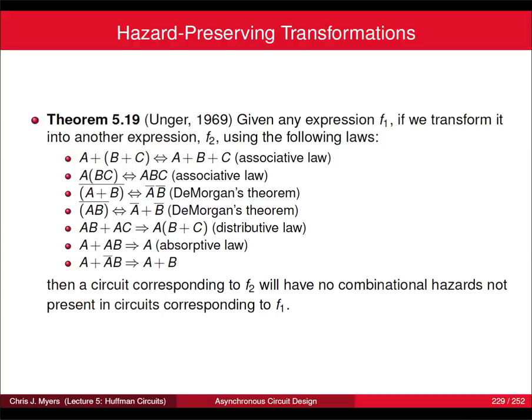But it's a good point that some simplifications are okay, but simplifications where you say, oh, I've got this product, it covers some minterms of this product, and then you go, okay, well, I don't need that product because it's only covering redundant minterms. That's not okay because we added that product to remove a hazard.